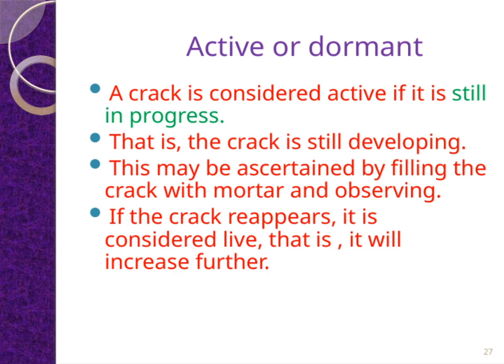Active cracks suggest ongoing movement, whereas dormant cracks are stable and not likely to worsen. This distinction helps us decide whether repairs are urgent or can be scheduled later. Keep in mind, continuous monitoring is key to managing these conditions effectively.